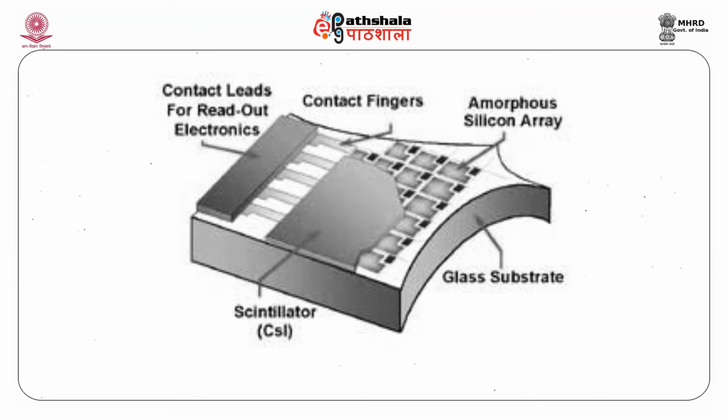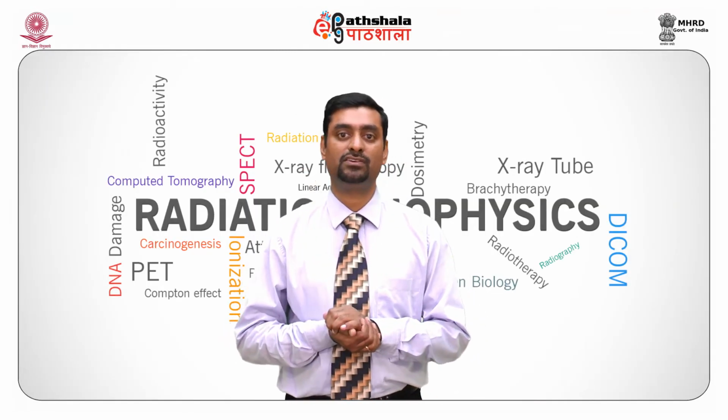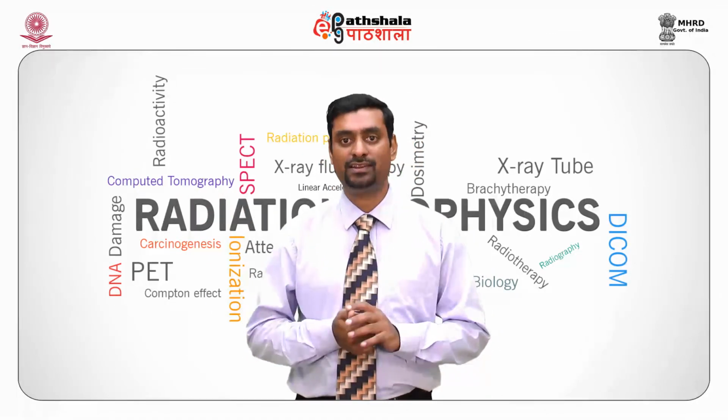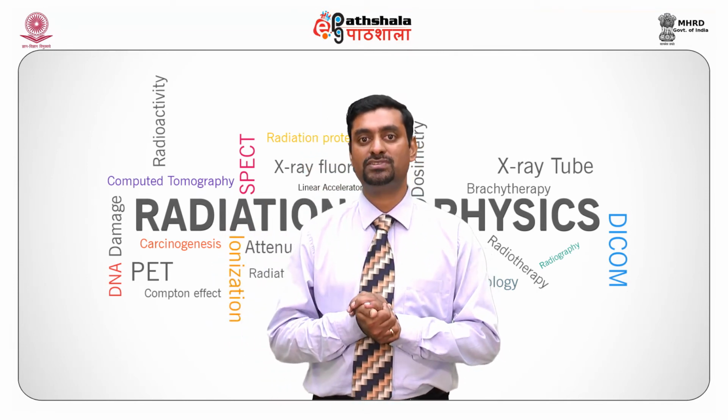The work of this amorphous photodiode array is to convert light to electrons, and it actually forms a bucket of electrons for each pixel. The TFT acts as an electronic switch. It collects the charge from the photodiode at every pixel and reads it out into the electronic system, and this can be directly displayed onto a monitor. The advantage of amorphous silicon technology is that it can be used for bedside radiography. Nowadays we get cassettes which have this kind of flat panel detectors based on amorphous silicon.